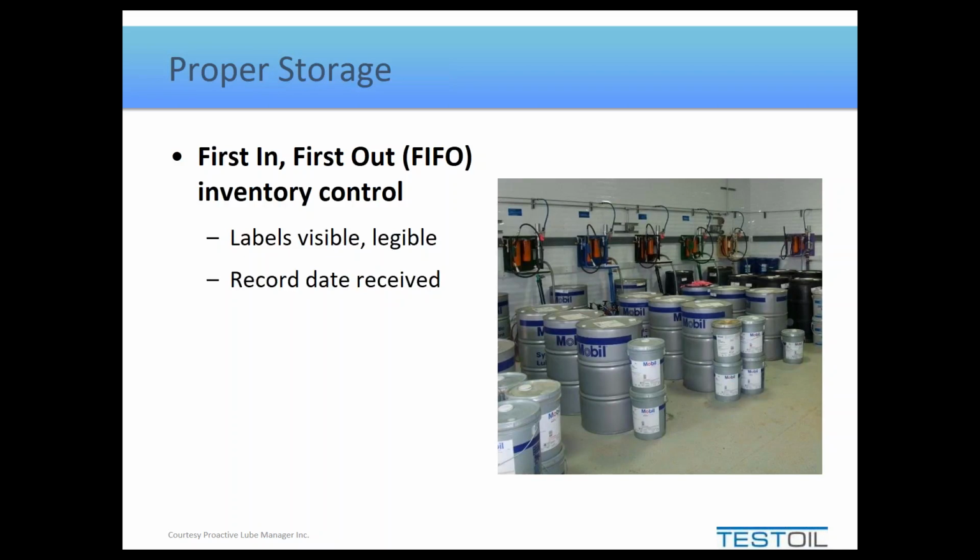On the walls, they installed rack-mounted filtration, which has 2 levels of filtration. So you could install a coarse and a fine filter. You could install a particulate and a water filter, whatever you want. But the drum that's closest to the wall can be hooked up in kidney loop to circulate the oil through the drum. And it takes maybe an hour and a half, 2 hours to filter an entire drum of oil. But they would pre-filter the oil so that the drum that was in play, the one that was open, had oil that was already meeting the ISO target for the systems.